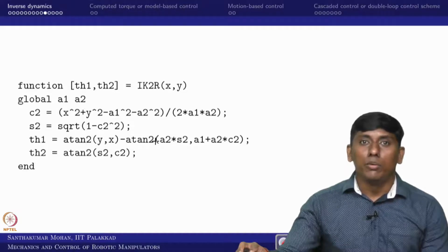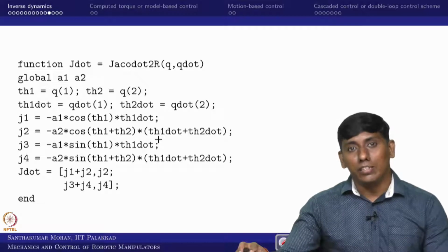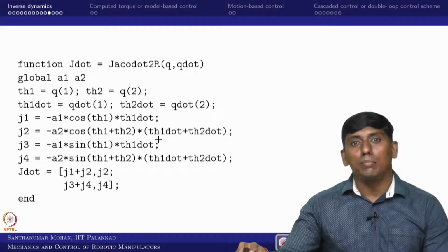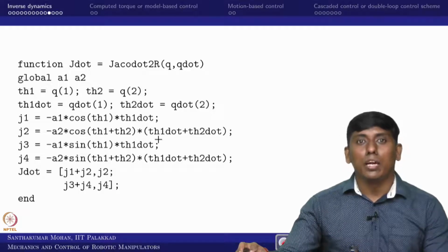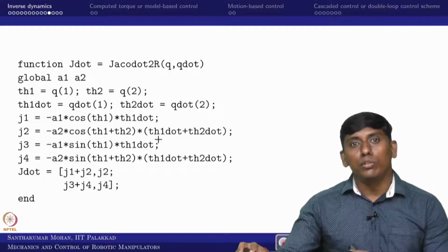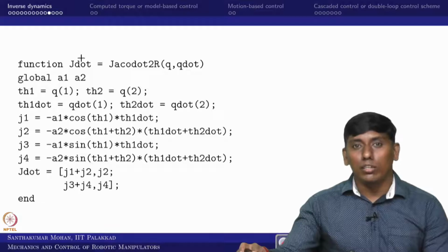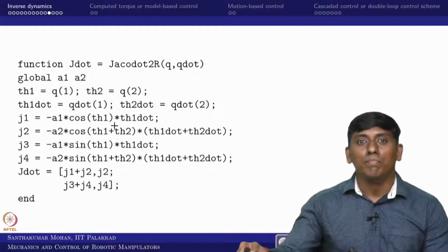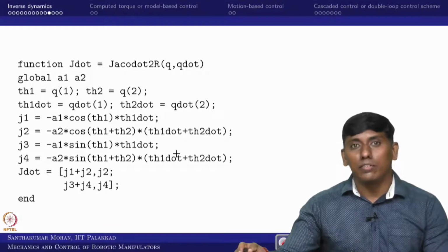can use it. Based on that, we come back with one additional variable, which is J dot, because q double dot desired can be derived in that way. For example, take mu dot equal to J of q into q dot. Then you can see mu double dot can be written as J of q into q double dot plus J dot into q dot. In this sense J dot is required, so we derived J dot based on the time derivative, and then we got this additional subfunction.